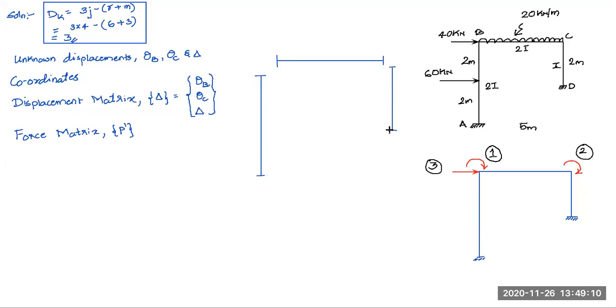So these ends are not allowed to displace in any direction. They have been restrained now. Okay, so we are providing the fixed support in all our coordinates. Mainly we want to restrain the displacements in the coordinates here initially. Now my displacements in the coordinates have been restrained, that is at B and C, where the coordinates were. So at B and C, we have put the restraints here now. The other loads which were there will be as they are.